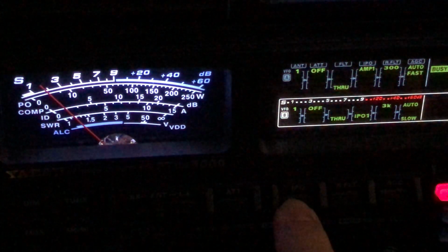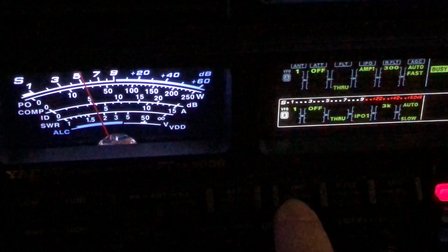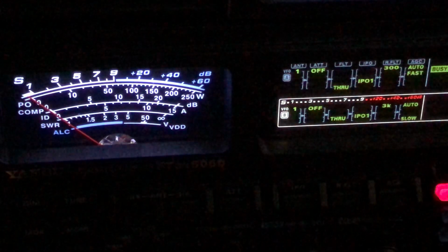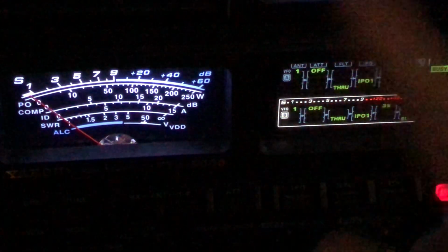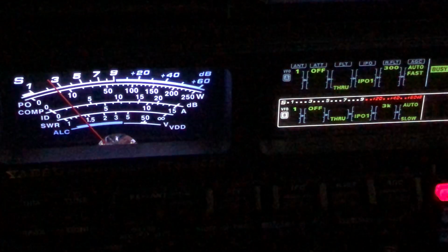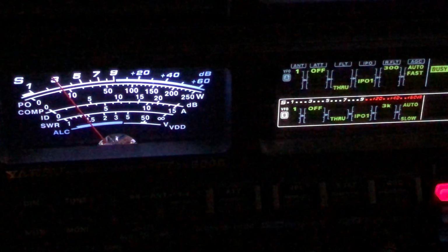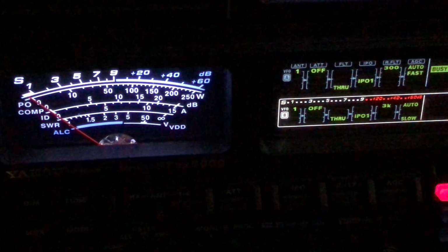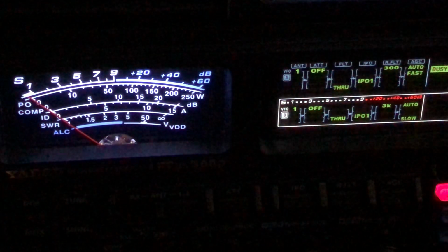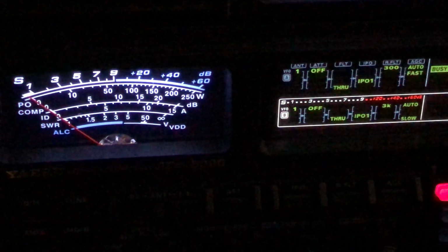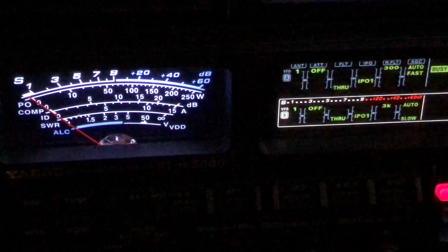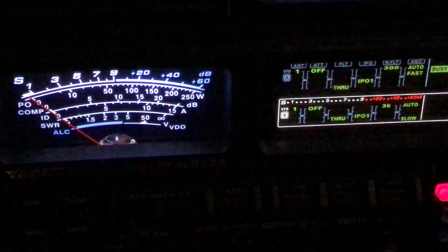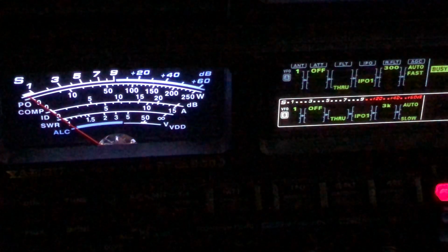Look. Listen to the noise though. See, it knocks more noise down than it does him. Yes, his signal dropped, but I hear him better over the noise. And see, now I'm going to kick in the DSP. That's just digital noise reduction. Now the 50 hertz filter, I'll even widen it to 100. And the audio peak filter for icing on the cake. Not moving the meter, sounds like a 599 to me. So that's why you can't get too hung up on an S meter.